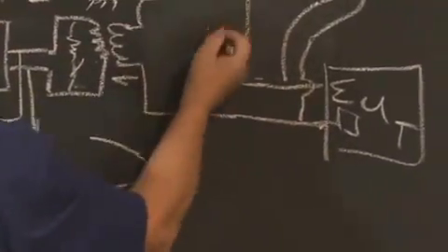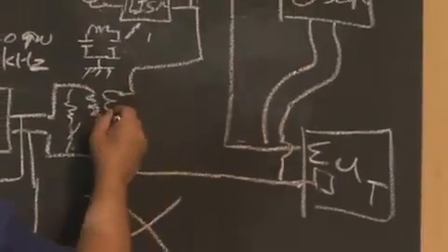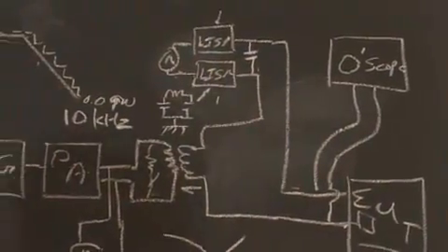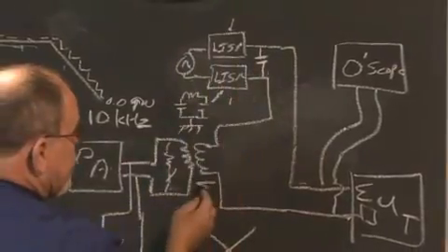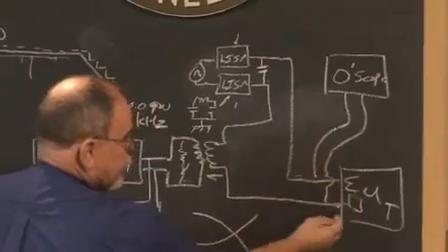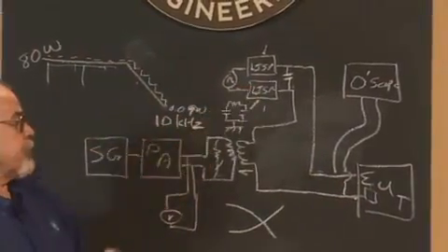So they cancel each other. The capacitor now acts as a short circuit for this signal and a high impedance for the 60 hertz. So our power loop stays the same, our injection loop alters its path, but allows the voltage to be dropped across the test article, not through the setup circuits or the listen.